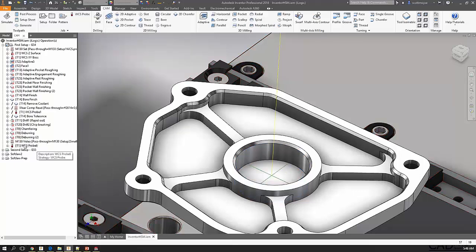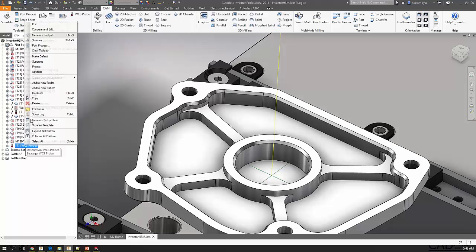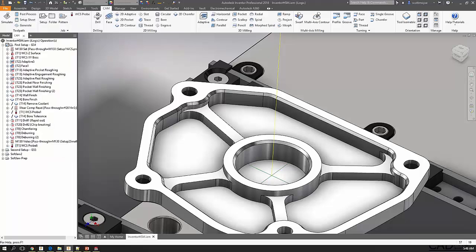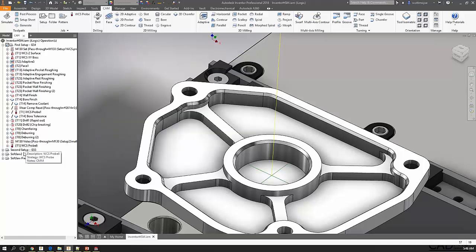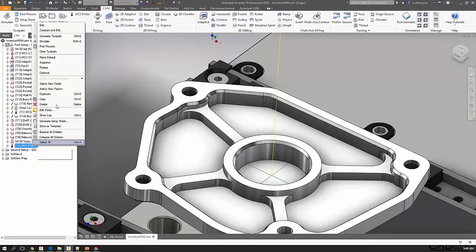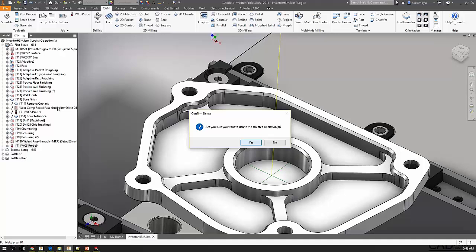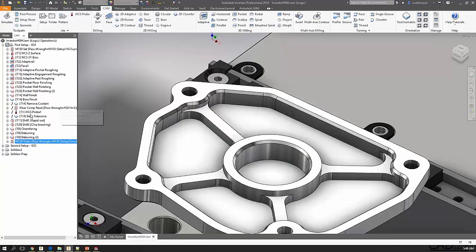And then in our case, we chose to use the notes and just add the tag CMM, and that's all that's required to switch between a WCS probe and a CMM probe. And then we come back, pick up exactly the same tool as before, and remachine the bore.